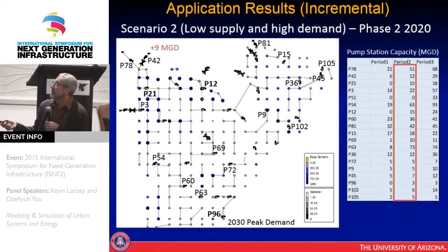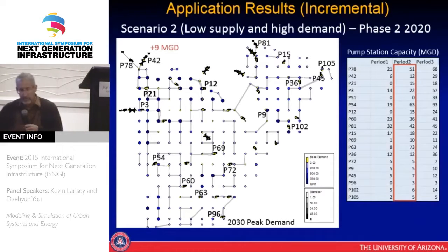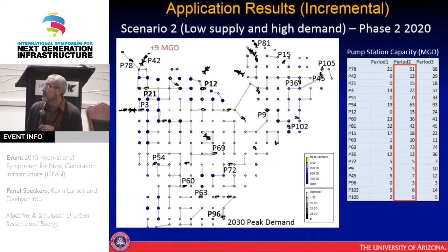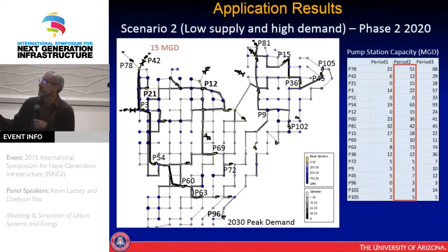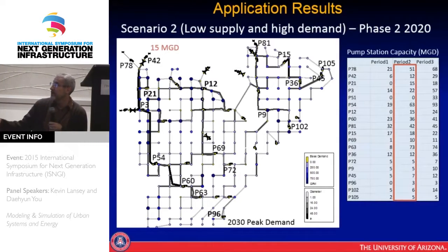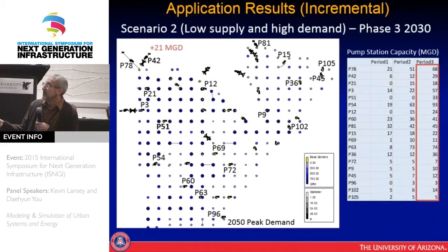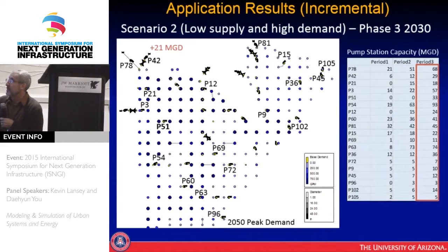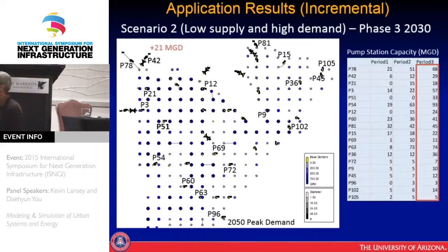Period 2, the second period, is from 2010 to 2020. Then the next 10-year period, and finally a third 20-year period after that, for a 40-year life overall. In the second period, we added a few pipes, not very many, and additional capacity up in the upper corner here. The result after period 2, in 2030, was a 15 MGD plant here and significant pipes again. It looks pretty similar to what you saw a minute ago. In period 3, we increased capacity again up in the satellite plant. We add very few pipes, but we add some pump capacity as we go through. So we put a lot of pipes in the ground initially, and then just add pump capacity and wastewater plants over time under this scenario.